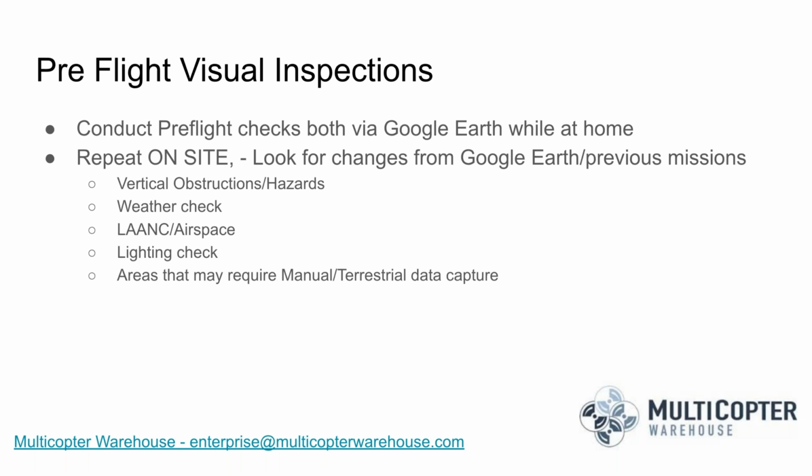So yes, Maps Made Easy, totally valid option. How does Pix4D work with thermal images? Can it handle radiometric images? It needs to be a radiometric image, which is something that a lot of folks aren't really familiar with. They think all thermal images are the same, but some are non-radiometric. You get more of what we'll call a qualitative hot-cold information, but not an actual temperature. And so Pix4D can process thermal images that are radiometric.